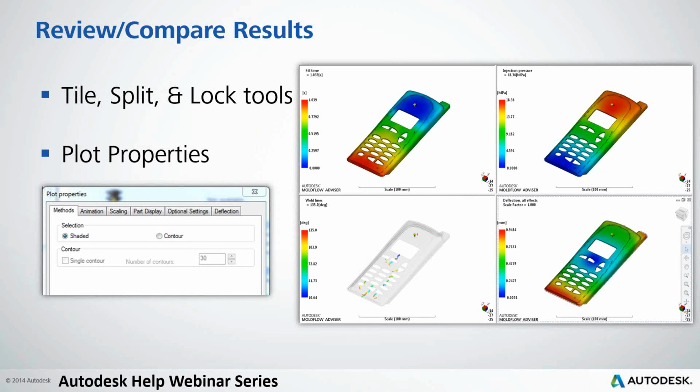So say you're looking to investigate those weld lines a little bit more, so you want that fill time result right above that. Or if you want to look at the deflection, to understand that a little bit further, you can use that fill time and injection pressure plot to kind of look into that a little bit further. And you're also able to control plot properties such as animation, scaling, and things like that. And we'll go into a brief demo on those as well.